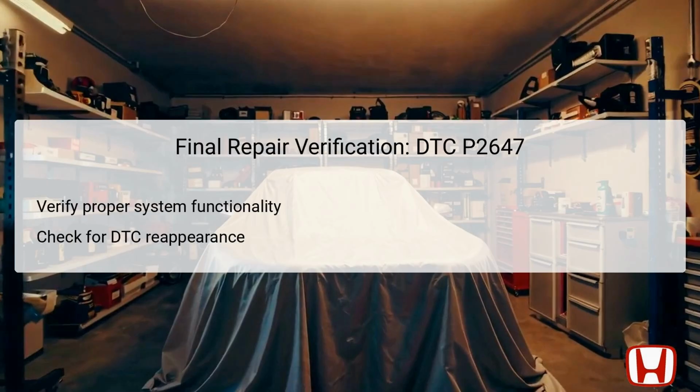Finally, after completing all troubleshooting steps, it's vital to verify the repair results. First, ensure that the VTEC system is functioning correctly by observing engine performance and checking for any signs that align with the DTC. After repairs have been made, clearing the DTC will help to ensure that the vehicle's system resets appropriately. Monitoring the vehicle to check for any reappearance of DTC P2647 is essential.